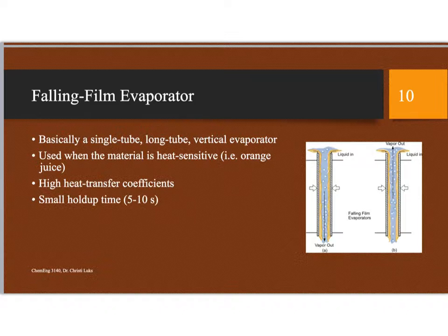You do get high heat transfer coefficients with this, and there's a very small holdup time, so the material will not stay in the device for very long, just simply because you're allowing it to fall due to gravity.